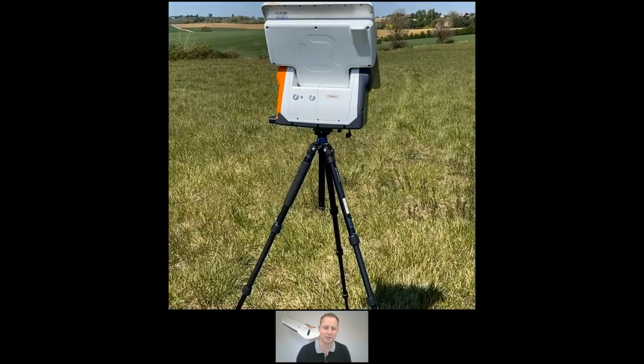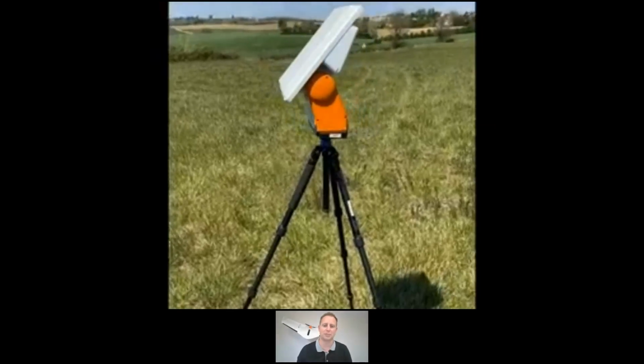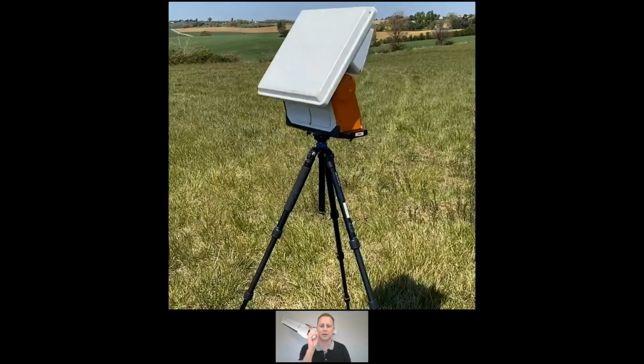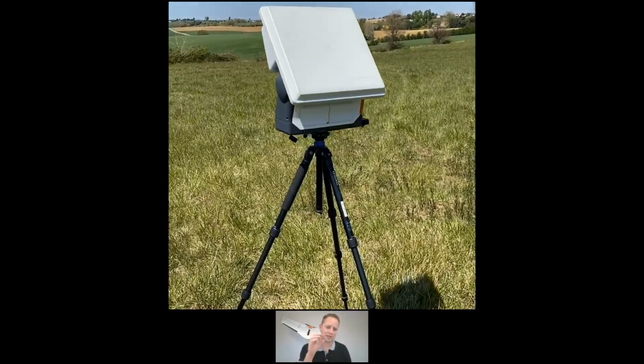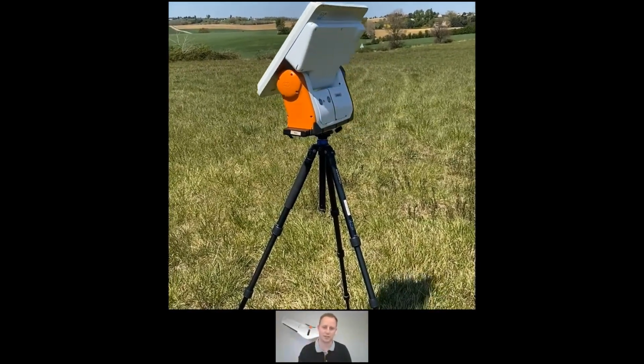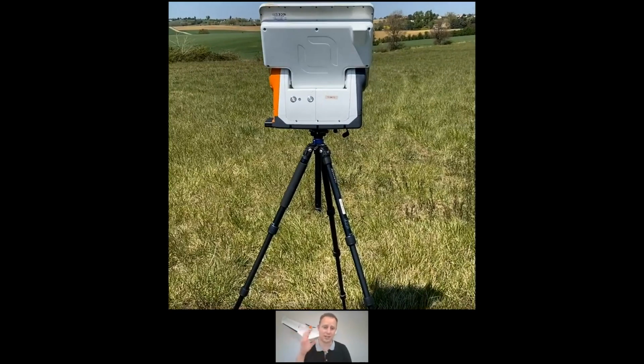operating this. Your drone's not flying that fast, but as you can see, it's a directional antenna, and it does auto tracking. So that's critical to get the kind of range that we're talking about here, because by being directional, we can concentrate the signal better, and we get a better and stronger return between the aircraft and the antenna. And by tracking, we always maintain that, and it does auto track. You don't have to worry about some joystick to try to keep track of it yourself.